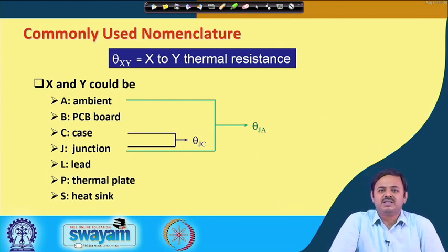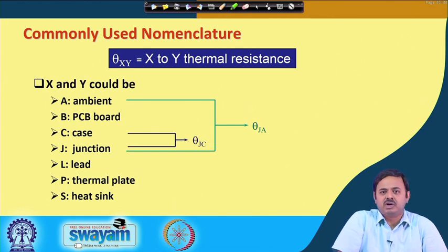So, let us say somebody said, what is theta JC? If you are a thermal designer, many people will ask for any new package that is designed, any package architecture, somebody will say, achha, what is the theta JC for this package? And you will say, oh, theta JC, I think that is typically around 1.1 degree C per watt. Oh, is it so? Okay. What is case to ambient? And you would say maybe like 2 degree C per watt. Okay. So, something like that.